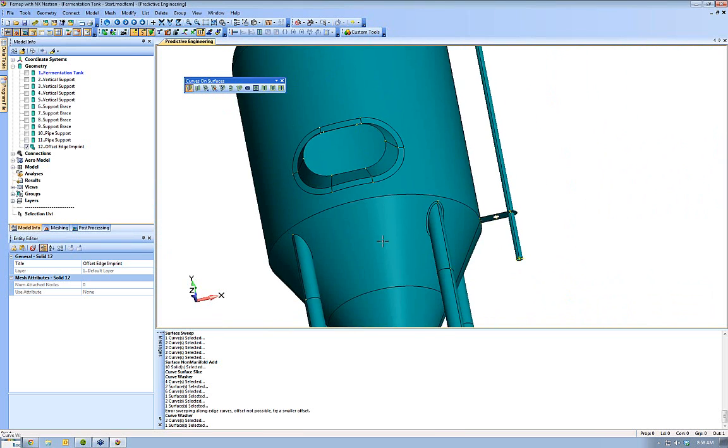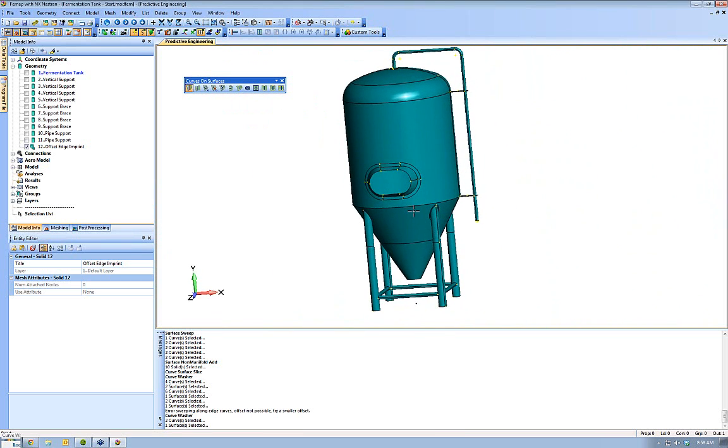At this point, I'm going to put a mesh size on my solid and mesh it. And any other commands that we're going to play with, we'll do within the meshing toolbox. And we can use those after it's been meshed because they will automatically update the mesh. These commands here do not update the mesh. So if your structure is already meshed and you start using curves on surfaces, you'll be modifying the underlying geometry, but your mesh will not be updating. So I'll just park this up here.